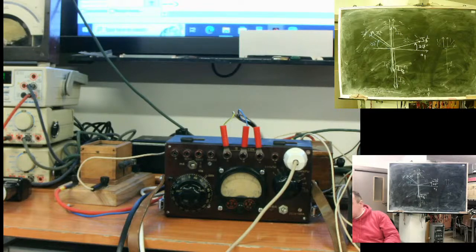First thing you need to check is a zero sequence voltage. If zero sequence voltage present, we see an earth fault. For example, here in rig, at earth fault at 10 kilovolts will have magnitude of 1 kiloampere. It's done artificial because we have low earthing for distribution network here.